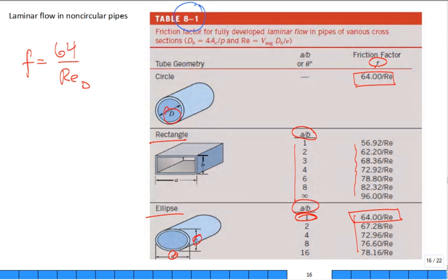Same with airflow and ducts. They fight to get as much air into the room, and they want to put it through a very minimum head space between the ceiling and the next floor. They can't put big ducts in there, so they put as big a duct as they can afford to put in there, but they move the flow pretty fast without making a lot of noise. And so it's a trade-off, but anyway, it's turbulent flow.